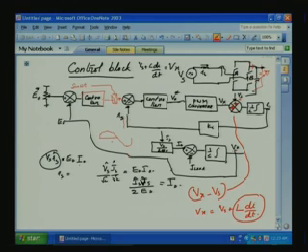Okay. Now, how to find out the controller? You have to find out the controller, and then represent the PWM converter, so that we can choose the controller in such a way that we get a very good response. That means, for any change in the input, the feedback current will follow it as quickly as possible. The converter, as we said, is a sine triangle converter. So, let us go to the next page.